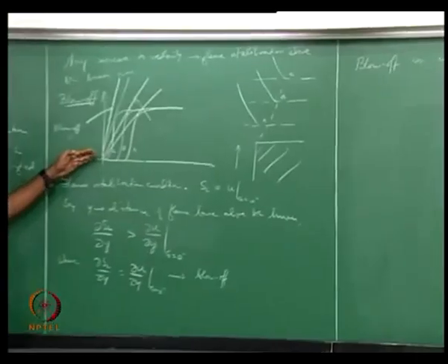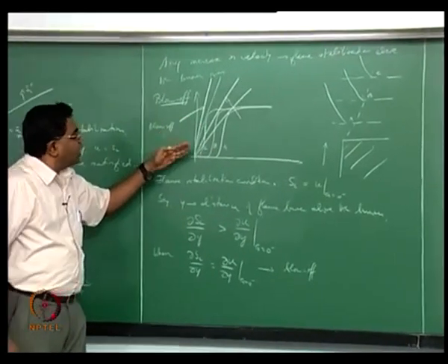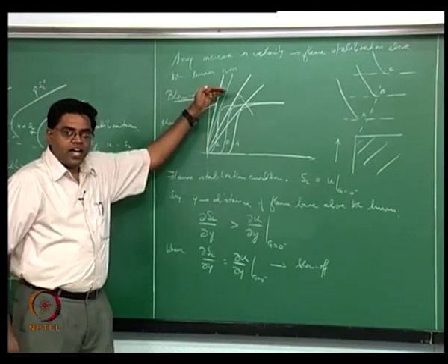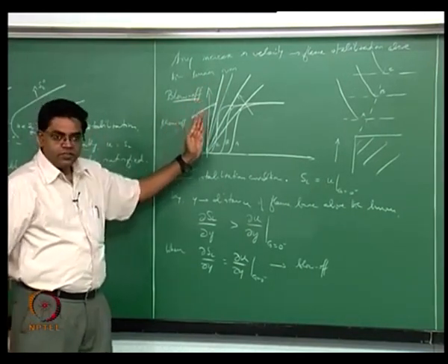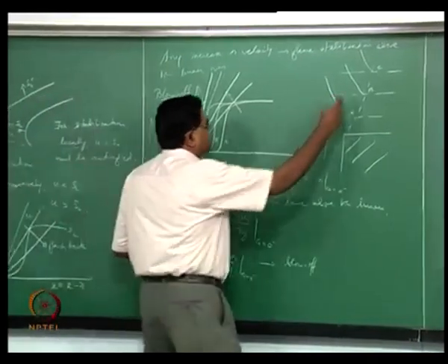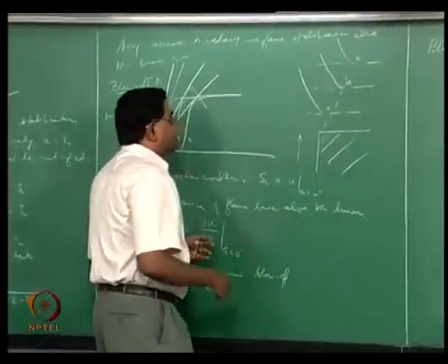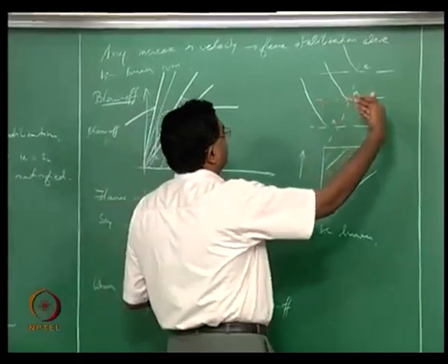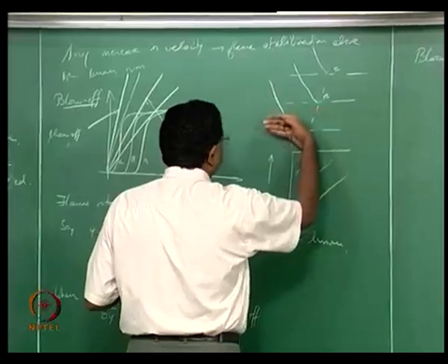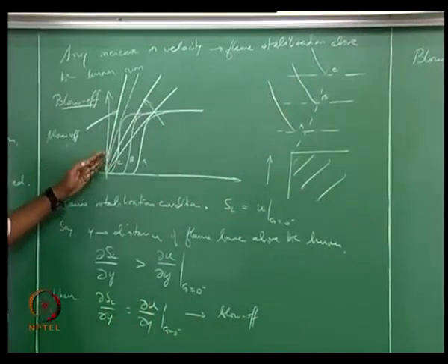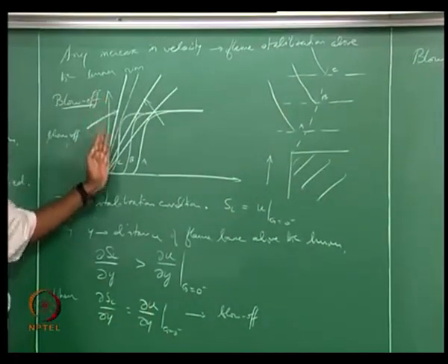The SL is actually more quickly rising to its high value closer to the flame base. Okay, so the flame base is shifted over to this point, and the SL, as we now go from the flame base, burner rim, you're now having a more drastic increase in the SL.